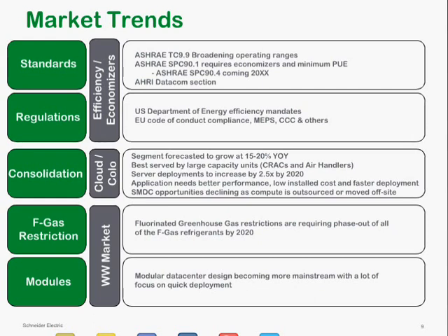So the decisions made in the cooling infrastructure and how to really make the overall data center operate efficiently are paramount. Another area that's really interesting is fluorocarbons. Countries like Japan, Denmark, and Germany have traditionally been leaders in this area. Over the past decade or so, we've basically eliminated refrigerants like R22. We've migrated to refrigerants like R410A and R134. But now we're seeing other refrigerants come into play with new mandates for eliminating or reducing fluorocarbons and greenhouse gases.